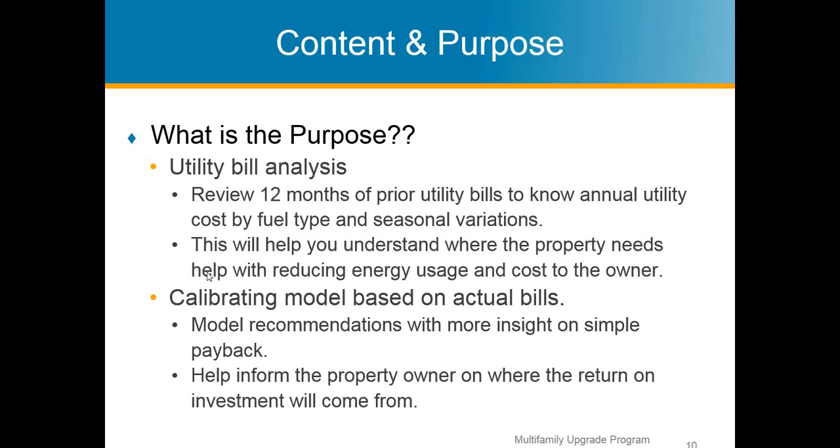You can also then take that utility bill information and you can calibrate your energy model based on the actual utility bills. Once you come back from your site visit, collect all your data, and you start building out your framework of your building. So you can model recommendations with more insight on a simple payback for knowing how much energy they use, what they can do to change, to upgrade, and then using that cost analysis to get a simple payback through utility bills.